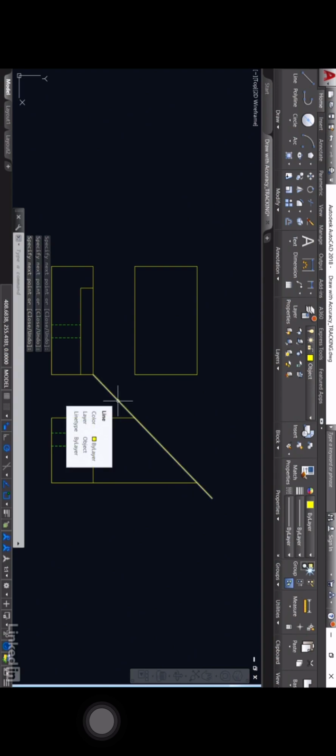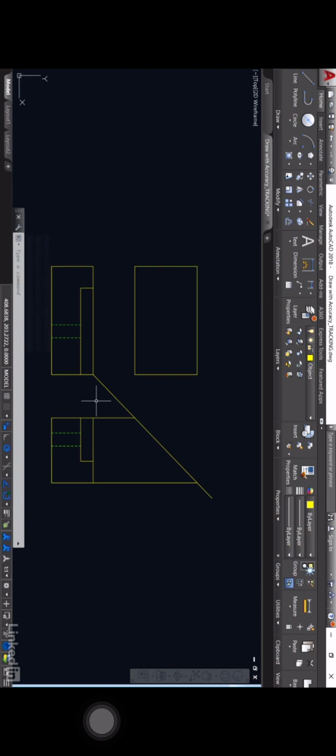That's really useful. So what we can do now is I can utilize this 45-degree line using all these lines here as well. So I can project another line up now. So I'll come off of the cutout line here, and I'll come upwards and I'll get an intersection there and click there, enter to finish. Now again, I can utilize my object snap tracking again. This is really useful. It really makes my life easier.